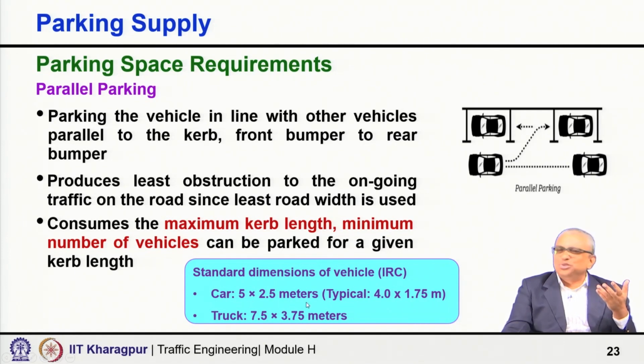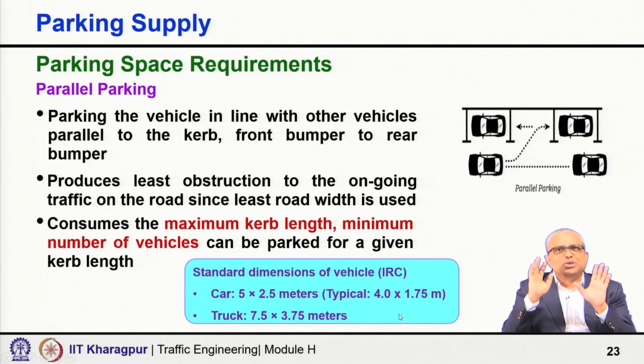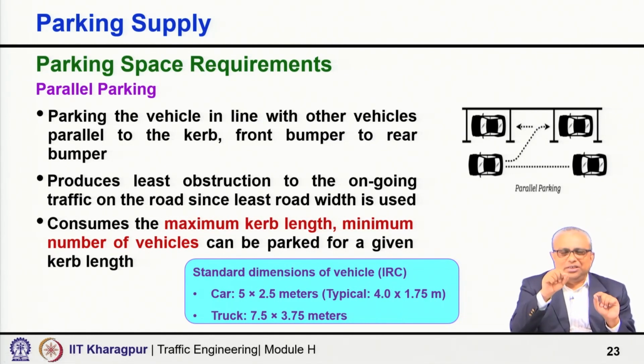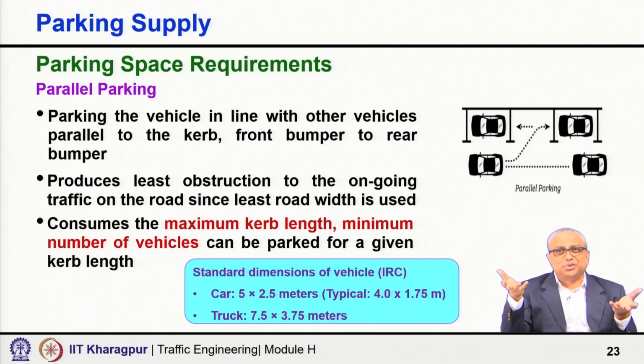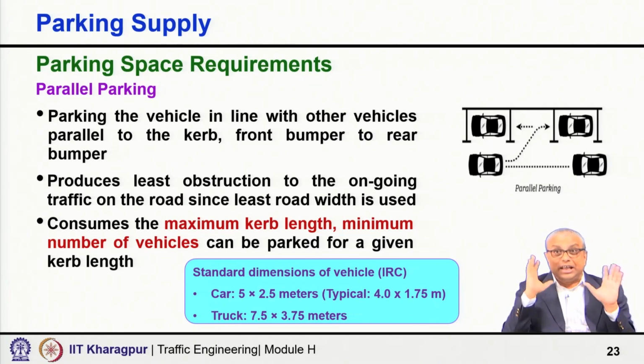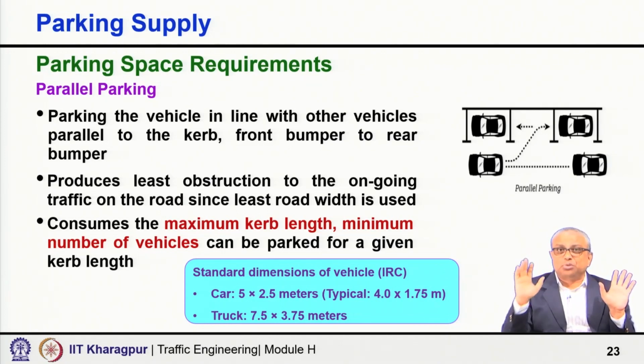So, really 2.5 meter is not the width of the car, right. Typically, the car width is 1.75 meter. So, here my objective is not to give you specification. You have to follow the corresponding, wherever you will work, what is acceptable, what is the actual traffic. You may follow Indian condition, you may follow IRC guideline, you may also deviate a little bit as per the context and take an appropriate value with justification, of course.